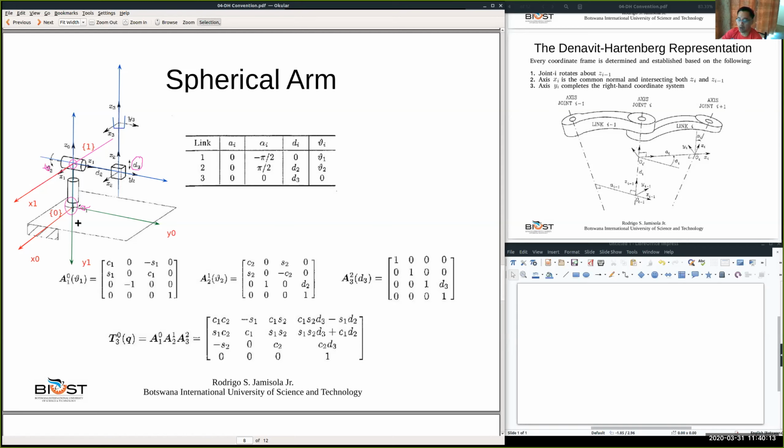So now it constrains our X2 to be passing through this point in order to intersect both Z2 and Z1. Again, because Z2 and Z1 live in this plane, we know that X2 will be coming out of that plane or going inside that plane as long as it is parallel to those arrows. So X2 can be here, somewhere, as long as it passes through that plane.